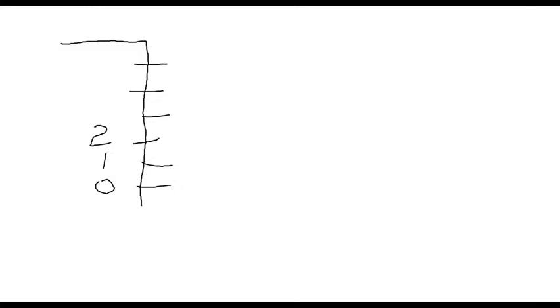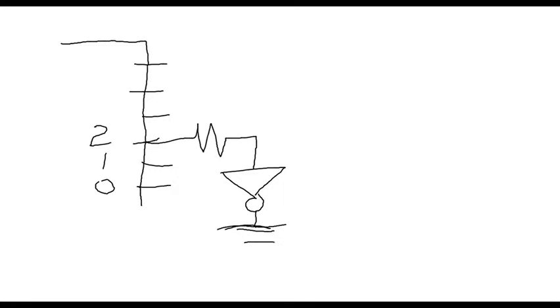Let us connect the LED through a resistor onto PB number 2. So there's a resistor, there's the LED, and the LED will be connected to ground. The value of the resistor will be perhaps 330 ohms. It's a good number. And that's the hardware that you would use to connect an LED to a Tiny 13.